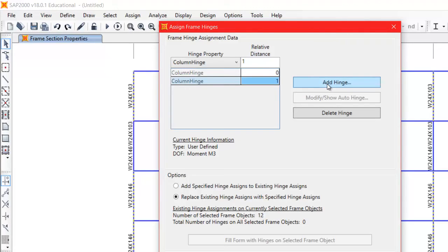Of course, in my model here, I'm not considering the panel zone, because I'm modeling centerline dimensions. If I have the panel zone, it's a little bit longer story because I have to break this one here, and then, if you remember the parallelogram model, I need to have small rigid members over here with some kind of spring. So it will take more time if you want to include it. So for now, I just excluded this one. So I have a hinge at relative distance 0 and at relative distance 1. That's it.